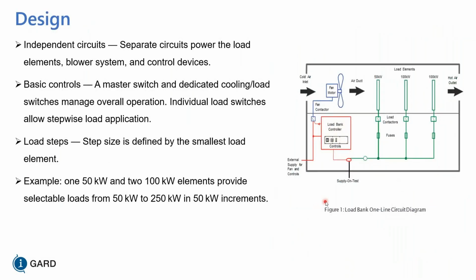So if we take a look at the circuit over here, you have a fan. This particular load bank is putting out as much as 250 kilowatts at 50 kilowatt resolution steps. So if all the steps are on, these are the load steps here. We have 3 load steps. It's a very simple load bank fused in your bus. So basically, you can have 250 kilowatts, so you're cooling down the resistors and creating heat for other types of devices to test. And your controller.